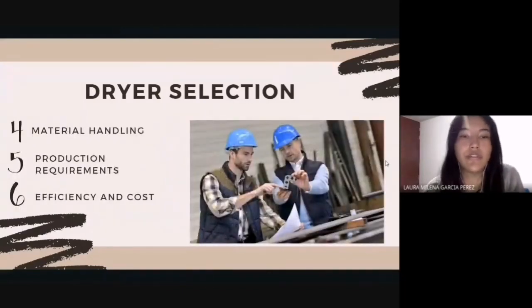Okay, and it is important to think about how material is handled, both wet and dry. You can use a non-stick surface and vibrating pallets to keep material flowing as needed. Cleaning accessories can also be important to incorporate to keep the system clean and remove any undesired material. It's also important to make sure that the dryer is correctly sized for the expected production quantities. If the dryer is undersized, it will suffer from adverse conditions, causing the product not to dry properly and suffer other quality control problems. And finally, an important part, of course, is the cost.